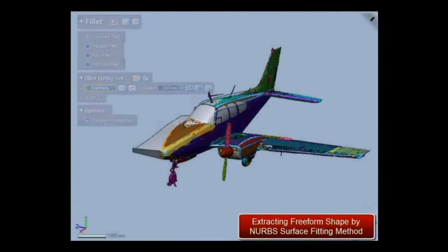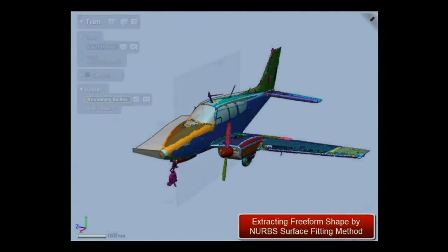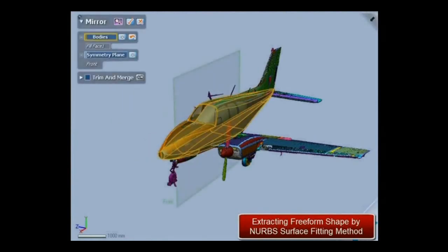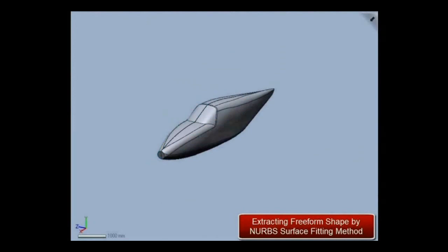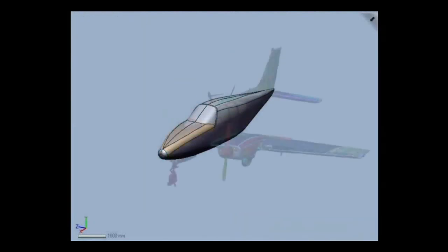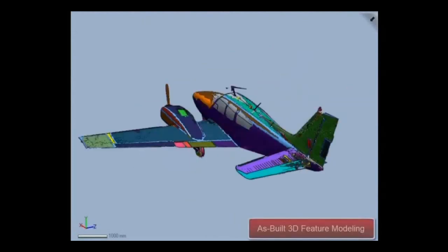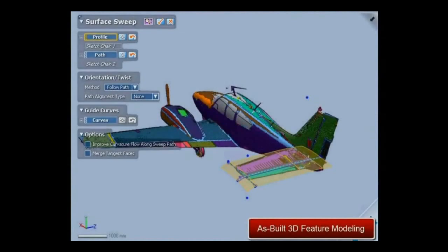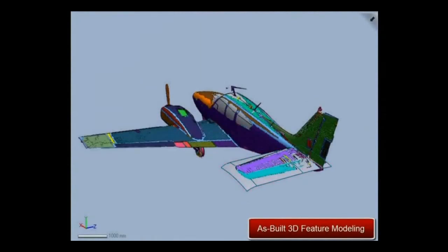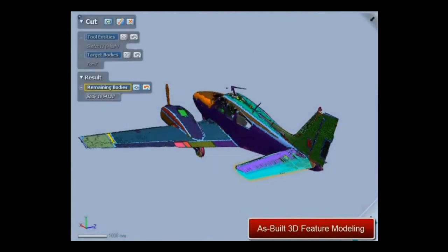And if the preview does not yet match the mesh enough, then we can also alter the sections and add another section, or move the sections in an interactive way. And of course, in case of simple airfoils, we can also use sweep surfaces to generate CAD-like surfaces.